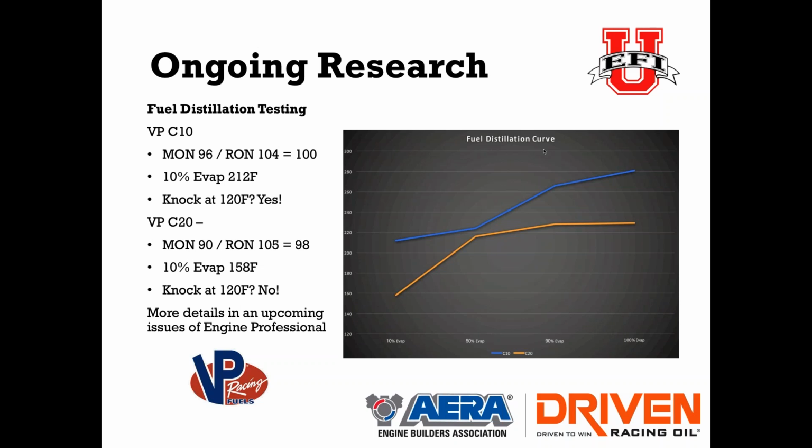So one nice thing you get here combustion-wise, for the guys who are real combustion gurus who might be watching: obviously if the fuel evaporates completely, you get 100% of the benefit of the heat of vaporization cooling effect, whereas if the fuel doesn't evaporate, then you don't get the full effect of cooling, and that raises your pre-compression temperature, which is going to end up with a higher compression temperature in the end, and that puts you closer to auto-ignition temperature. So there's a lot of things going on here.